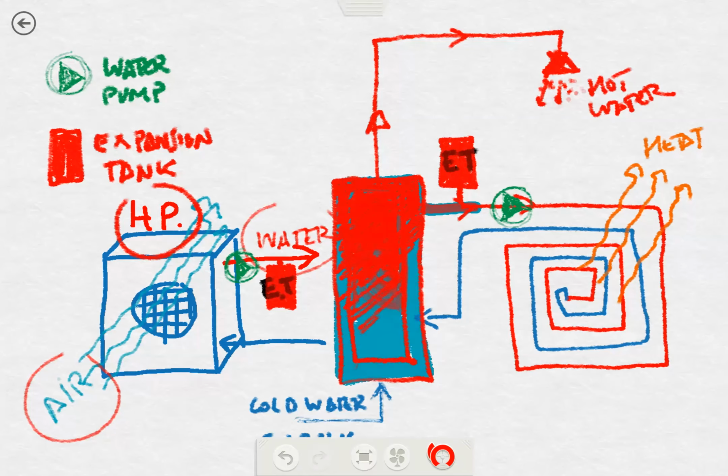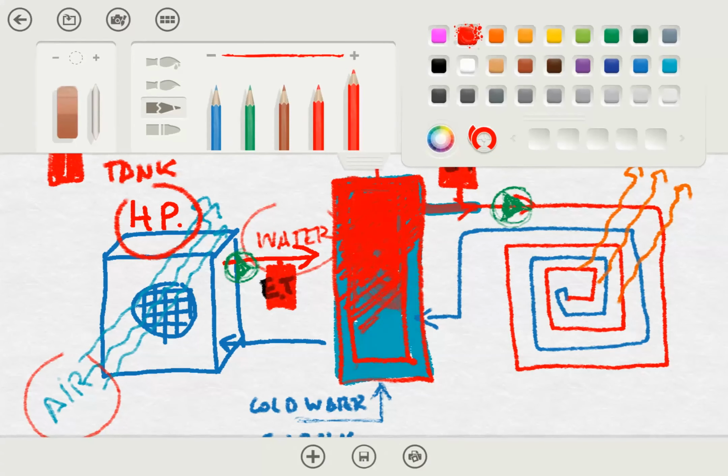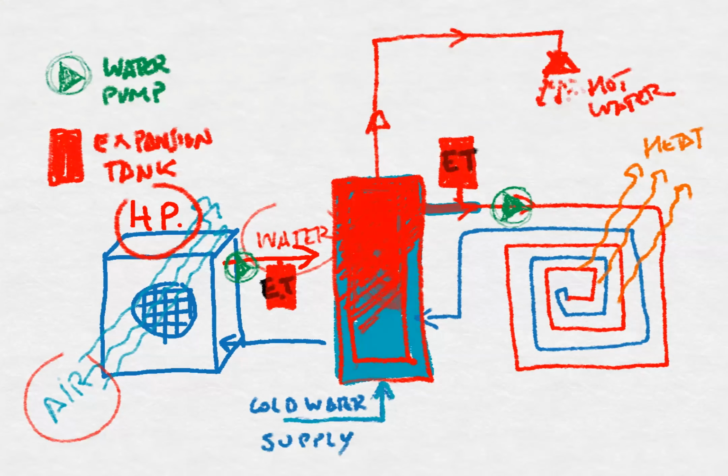Okay, so if we need to supply cold water, sorry, this is blue. If we need to supply cold water, we need to supply this water at the bottom of the tank. And if we need to release hot water, then we need to release hot water here.